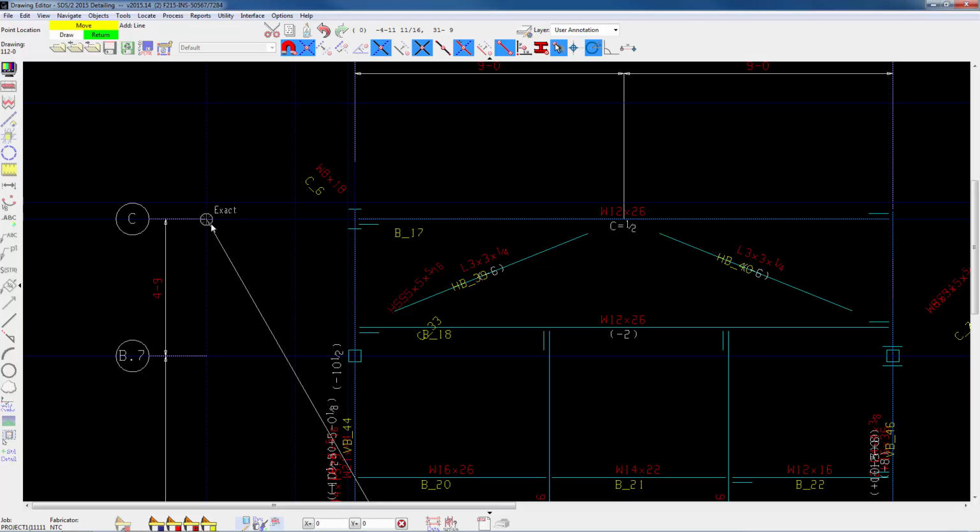It's picking a point down in the bottom of the screen, and it's going to draw a line up to this point here. So if I hit draw, it just drew a line from that point up. So I'm going to click on that one and hit delete. Then I'm going to do line again, and instead of hitting the left button to draw, I'm going to hit the middle button to move. So it's telling it to move my first point to that point. Now my second point, at this point here, I'm going to hit the left button to draw. Now it drew that line.